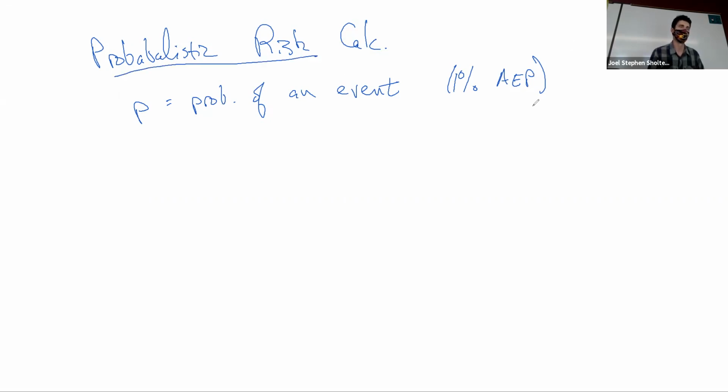I did that kind of risk equal to probability times consequence, right? That's a little different here, because we're only dealing in probabilities. So P is the probability of the event. R is going to be the probability of P occurring over n years.